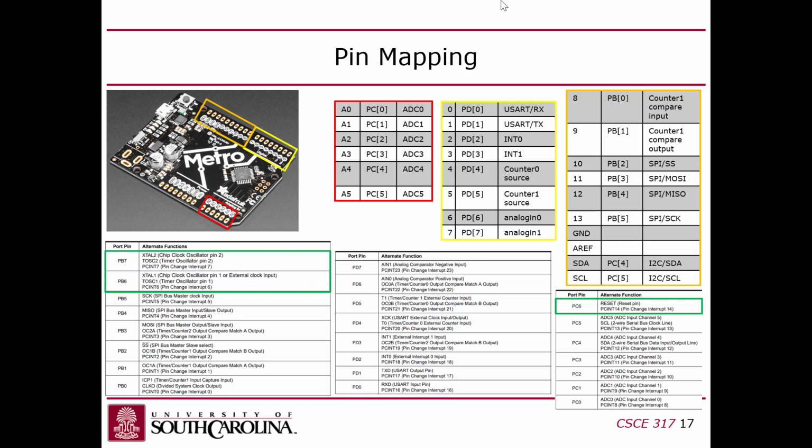I couldn't figure out where these things were going, because in the architecture, they call them just port B, port C, and port D. None of these names that they have in the silkscreen actually exist in the data sheet for the chip. This is all just manufactured by the Arduino people.